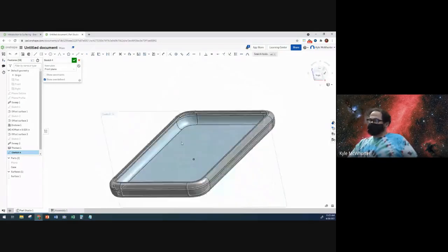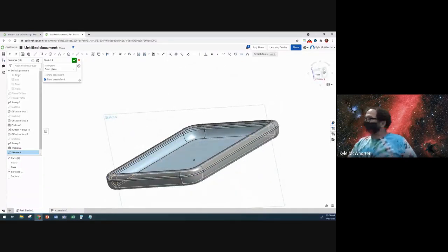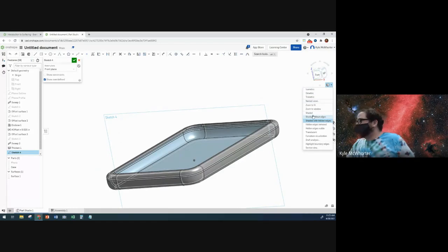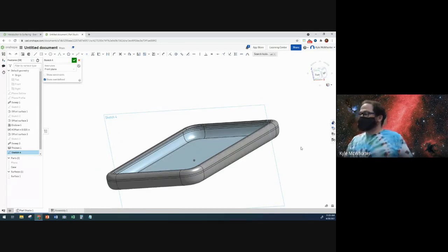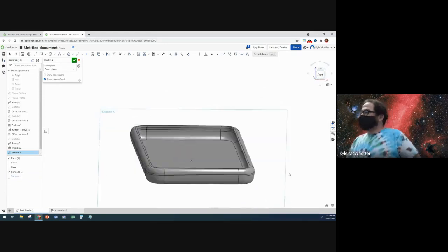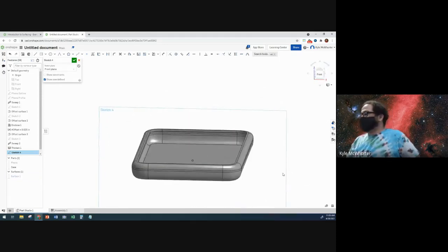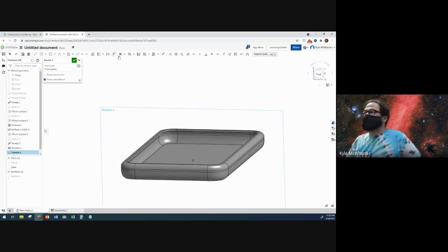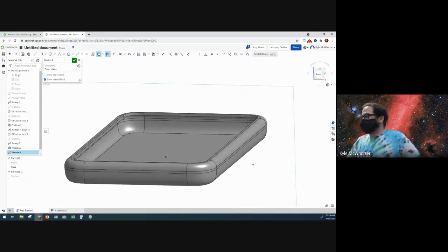And what we're going to do is we're going to select the sides that we would have to visualize which sides are going to intersect. And actually, I don't think I need this surface. I'm going to hide that surface. So we need to use, but we want it to be construction geometry.